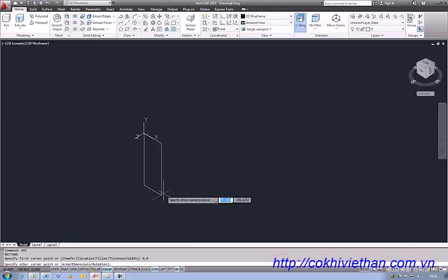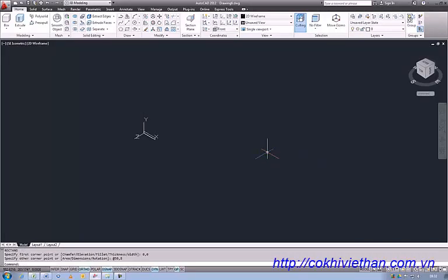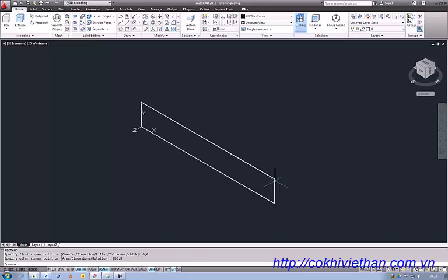So let's go back to AutoCAD. So our next coordinate is going to be 50, comma, we're going to use half the diameter of the bolt, which is 8, and then hit enter. I'm just going to zoom in down here, and there we have a rectangle which is half the diameter of our bolt. Now what we're going to do is put a small chamfer on two of the corners here, which is going to act as our 45-degree chamfer.